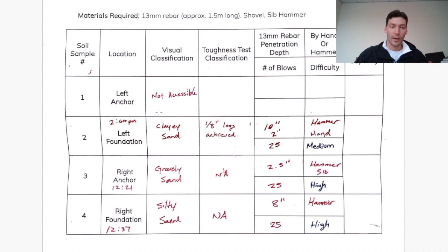And you can look up and research more about that, but briefly, the USCS classifies soil based on the grain size of the particles in that soil. And it's broadly defined in 2 major categories. We have fine grain soils and coarse grain soils, also sometimes referred to as granular soils.